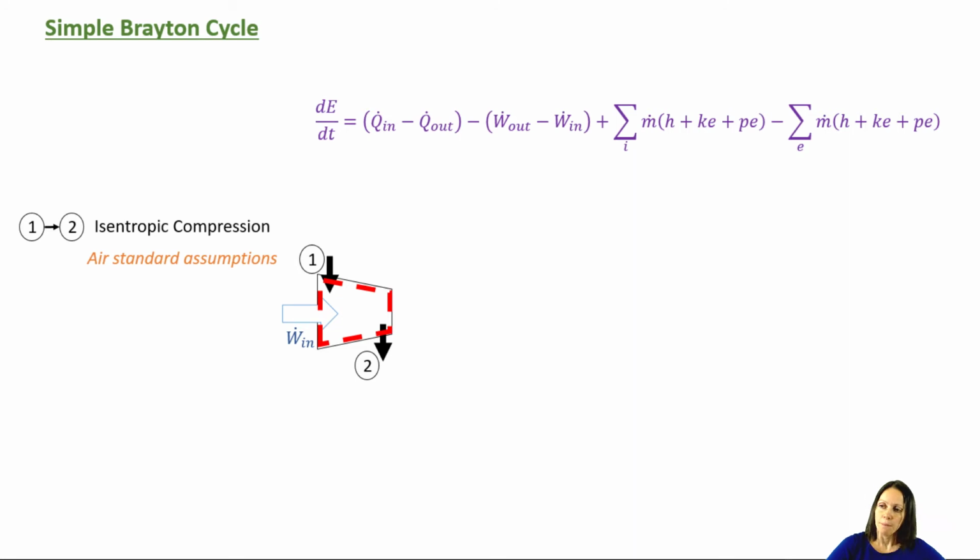I'm going to assume that this thing is operating at steady state, and that's usually a good assumption to make. The only time you couldn't make that assumption is if you're bringing it online or offline. It's isentropic, so that means it's adiabatic and reversible. Adiabatic means I can get rid of those Q's, and the compressor requires work, I'm not getting work out of it, so I'm going to get rid of that. And I'm going to ignore kinetic and potential energy changes.